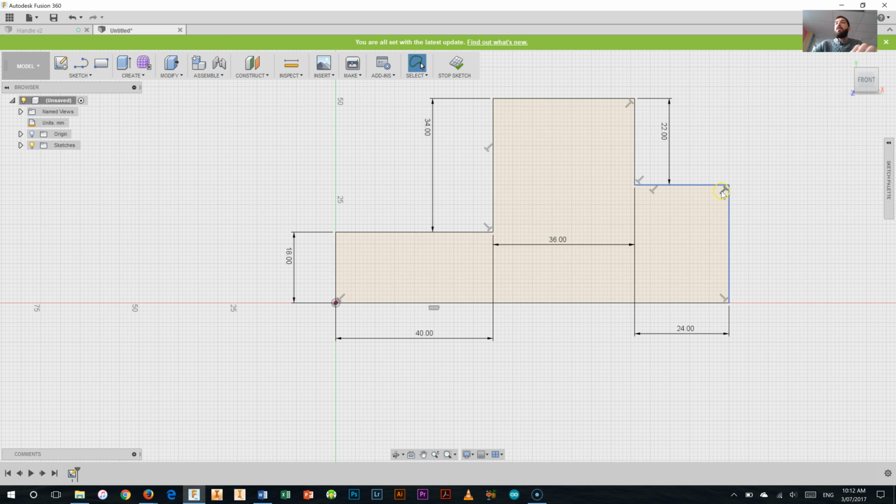You can also see that we've got a bunch of little, what look like T's in the corners of this drawing. And what those are is what we call perpendicular constraints. So they are holding all these different lines. For example, this one in this corner holds this top line and this lower line together perpendicular, or at 90 degrees to each other. So that's one of the constraints on this sketch. And the other one is the horizontal constraint down the bottom, and that says that this line here must stay horizontal. And if I hover over the very base point here, we've also got a couple of coincidence constraints there. So different lines are coincident together here.